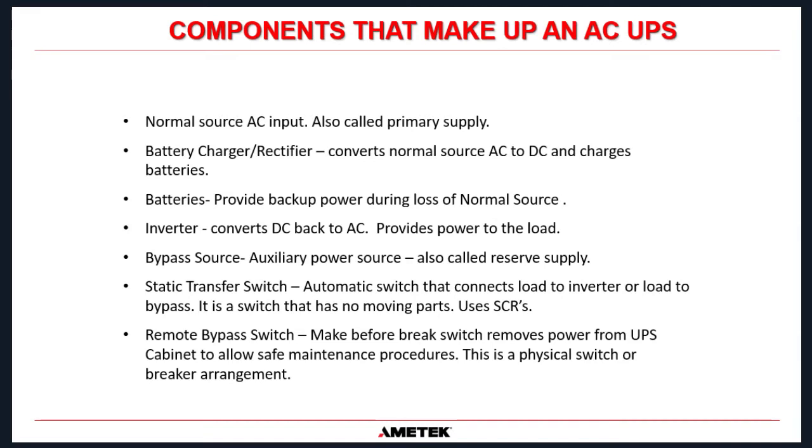And then we have a remote bypass switch or a bypass switch. That is a make before break switch. Usually, now there is caveats to that, but we're not going to discuss that today. But it's a make before break switch that removes power from the UPS cabinet, usually to allow safe maintenance procedures. And this is a physical switch or breaker arrangement. Okay.